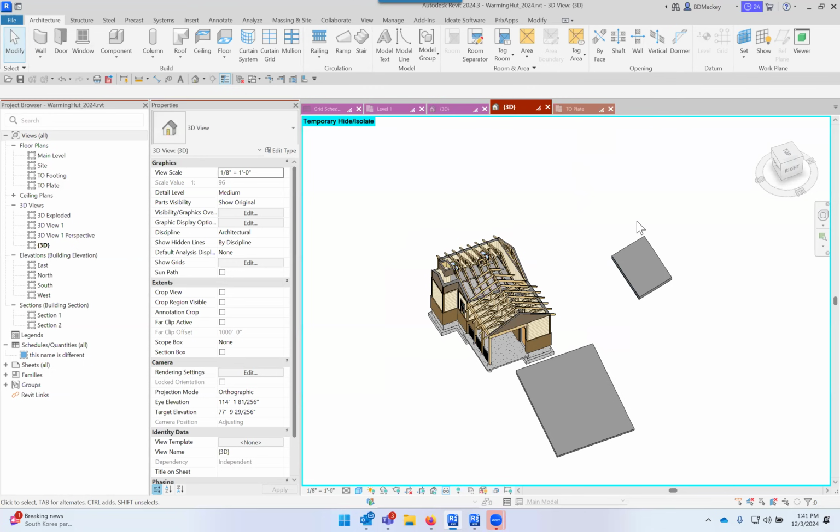That's about all I could think of because when you're trying to place that perfectly into a dome onto the center part, it is a royal pain to get face-based things to do that. I have nested that object into an adaptive component because an adaptive component will give you greater control on grabbing that grip. As you move that grip to line up with the reference planes, it will actually snap a little bit better. So you can grab the adaptive point, move the adaptive point, and as long as you know you're set up to be perpendicular to the host on that adaptive point, it should work for you as well. But when you start talking about hosting things onto a dome, it's a royal pain.